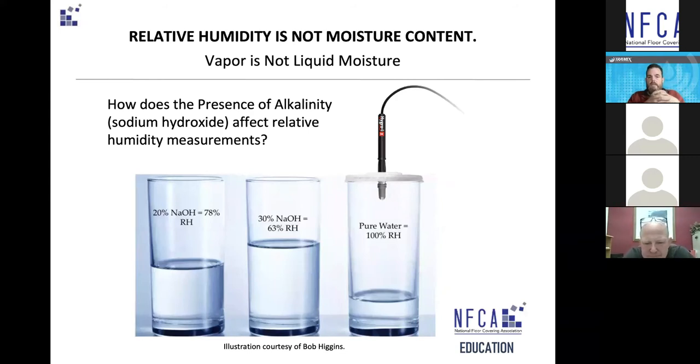They can. So if you have 100% water, the air above that water will become saturated. If there's salts in the water, then that saturation will reduce. Anybody who has lived by the ocean or by a lake can experience this exact phenomenon. If you live near a lake, the humidity is very high in the air. If you live by the ocean, it's not, because of the salt. Similarly, if anybody has used a calibration check plate, calibration salts for a relative humidity probe, they will understand this analogy.